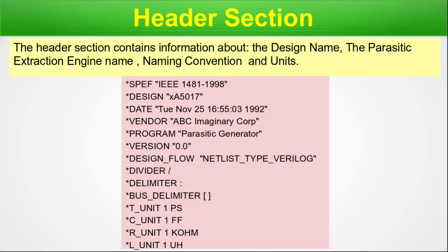So let's move on. Name map section. For multi-million gate design, the SPEF file will contain a huge number of nets interconnecting them. Thus, the SPEF will be very bulky. The name map section provides a way to use a shorthand method for net names, which are usually very long for a hierarchical design, thus reducing the overall file size. Let us see how.